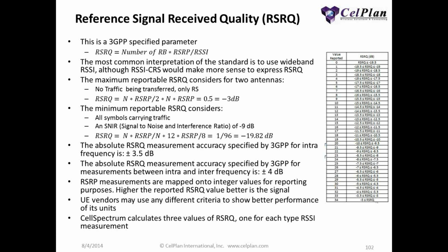Another 3GPP measurement that we also discussed in our measurement webinar is RSRQ. RSRQ is very important because it is used to adjust the modulation scheme and so on. It happens that RSRQ, according to the 3GPP formula, depends on RSRP, that's fine, but also depends on RSSI.